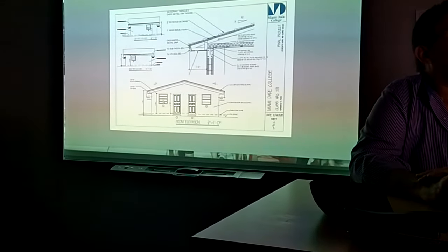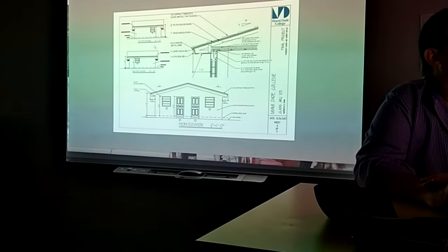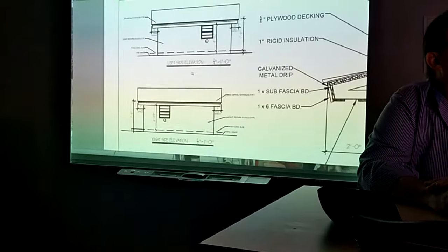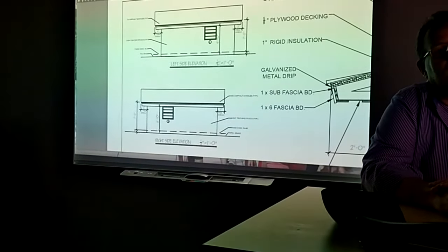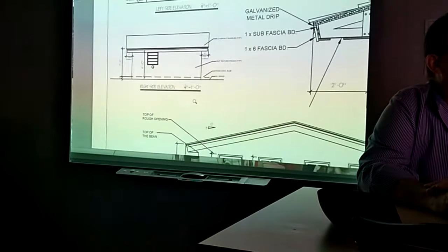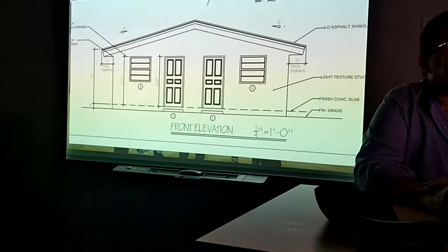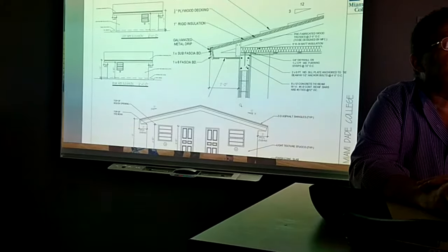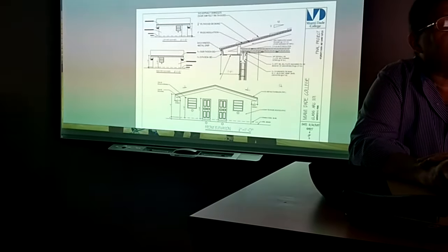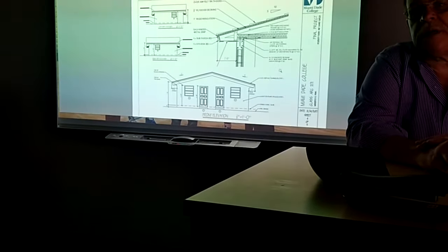There. See that? You got these 2 drawings, 1 at 1/8. That's why you need to change this at 1/8 on model space, so that your scales go accordingly. You have to coordinate all that. This one's at 1/4, and then over here, you could even put a title on paper space on the top. A lot of architects will do that.